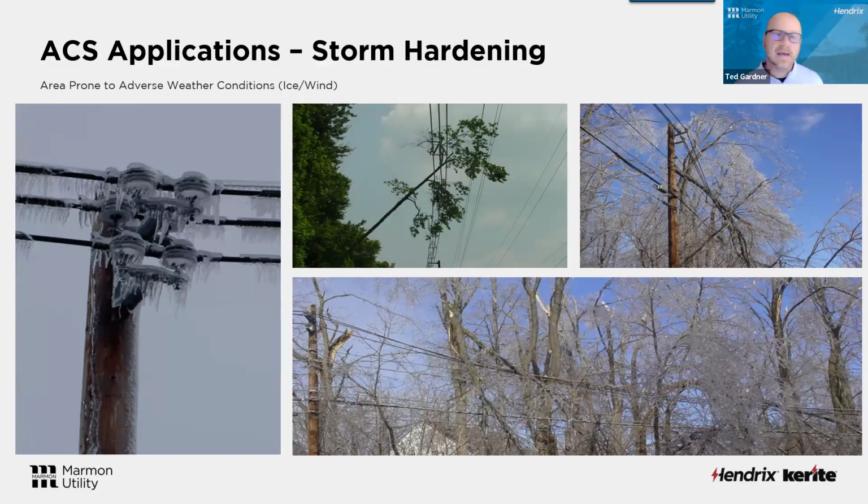The other thing is guy leads. With a spacer cable system, you're not going to be able to get away with those 12 or 15-foot guy leads that maybe you use on your ACSR. We try to get as close to a 1-to-1 ratio as we can with our guys. So, you may be looking at 30, 35-foot guy leads at a minimum. We want to build the system as strong as possible.